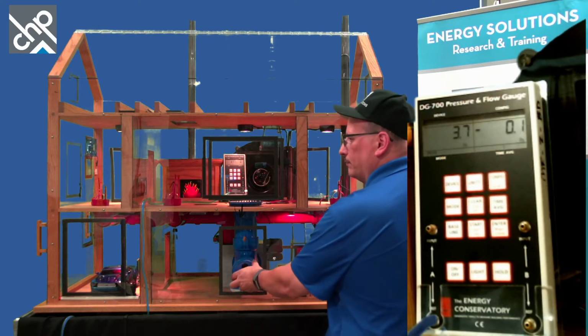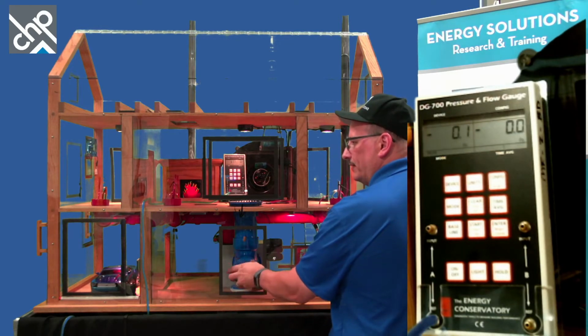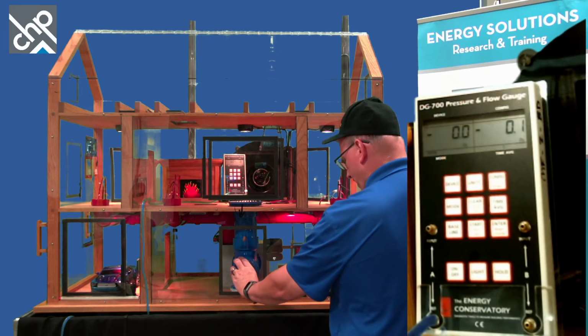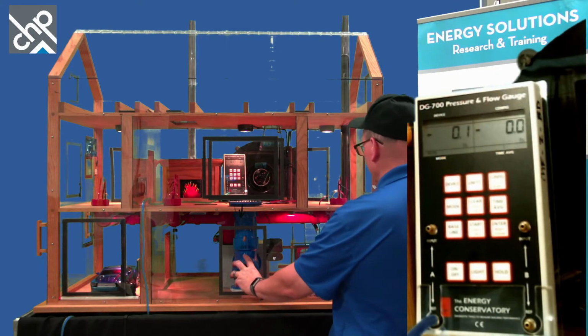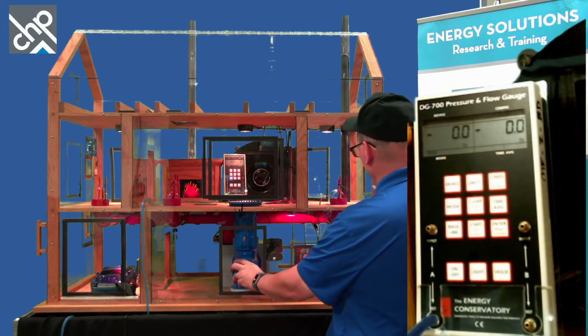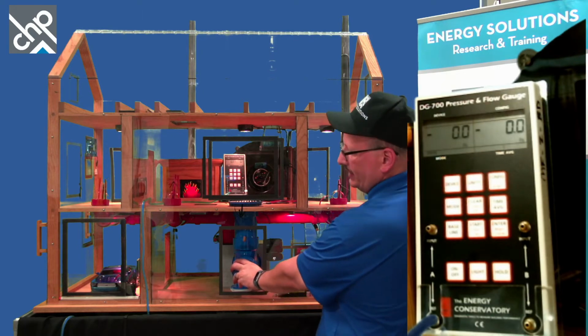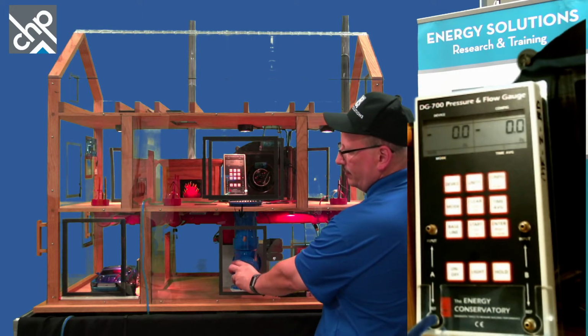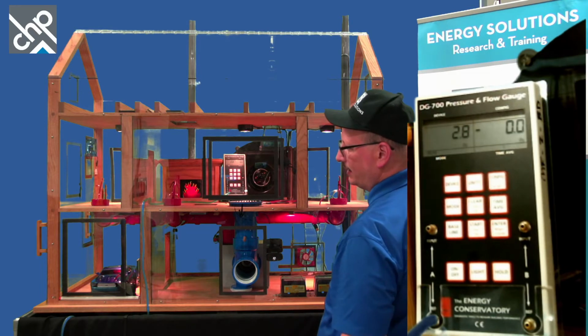So I'm going to put the leak back in here. Seal it back up. You see how it kind of slowed down. It goes out at a slower pace now. And then the manometer reading, you see how it bounced out. So I'm going to open that back up. You see how it goes positive.